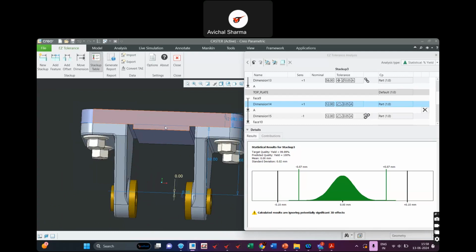There is an option in Creo called shrink wrap, where you can shrink wrap the complete welded assembly as a single part, and then introduce that in the assembly. That way you can consider it as a single part without any joints. Basically, welded joints are not joints which will be moving, right? Fixed joints, basically. So that's how we can work with welded assemblies.